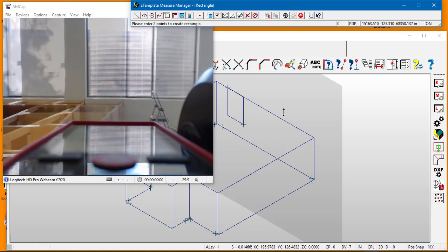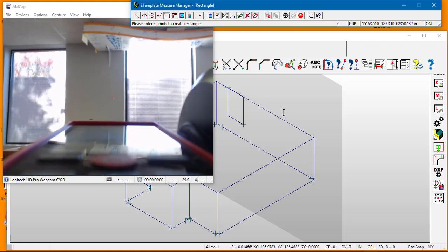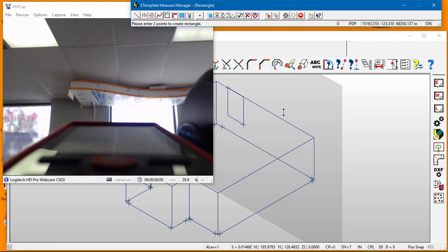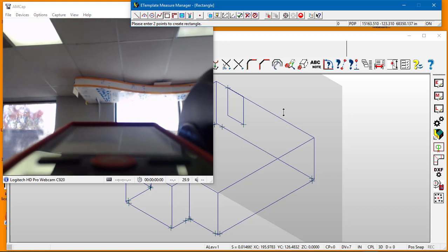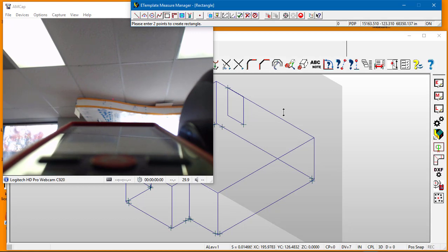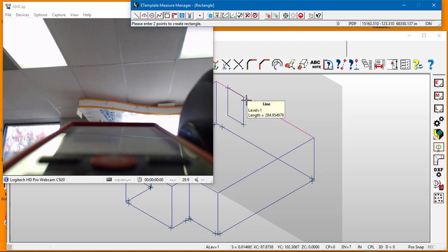And on this window, I have a soffit that's in the way. And I'm pretending to do the room as though the soffit weren't there, which would be a lot simpler. I'd simply point it at that corner just like I did the other one. But in this case, because that back wall is my working plane, if I set this beam on the ceiling, and I'm moving myself to position myself so that there's no parallax, I set that beam on the ceiling directly where that corner is, it's going to fall to this corner. So we'll go ahead and shoot that.